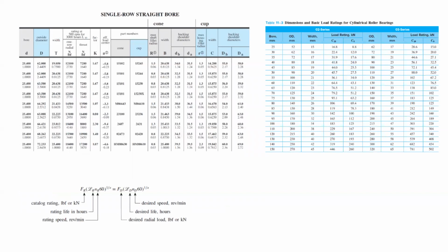So if you go look at a bearing catalog, it's pretty intimidating at first. It'll typically look something like this, where there's just a whole bunch of rows and you're just like, I want it to support some kind of load. Which one do I choose? There are two constraints that you usually want to consider. You're usually pretty space limited in terms of the size of your bearing. Just to use suspension again as an example, because I'm familiar with it, or unsprung, where you have the hub, it's constrained by the size of the wheel, right? You have to fit this whole rotating system inside of your wheel diameter while supporting a relatively large load.